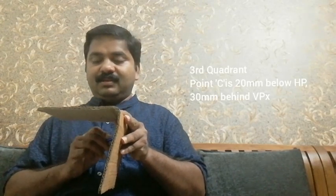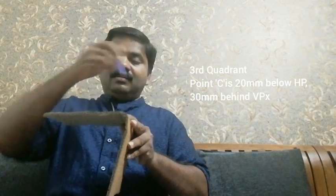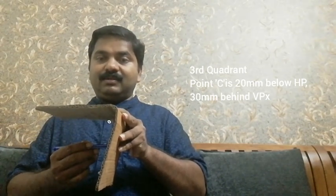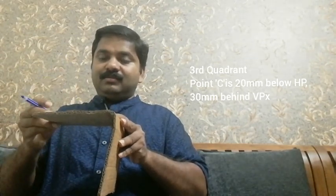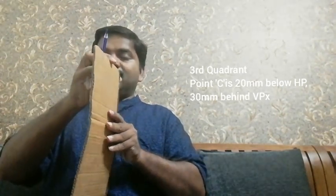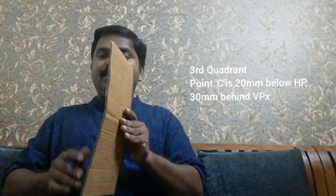Now this is the third quadrant. So the point is 20 mm below HP, 30 mm behind VP. The person is looking from this side. So the front view will be obtained here on the VP, 20 mm below this intersection line XY line, and the top view will be obtained here. After having obtained the top view, the HP has to be rotated in the clockwise direction so that the top view will be above XY line and the front view will be 20 mm below XY line.